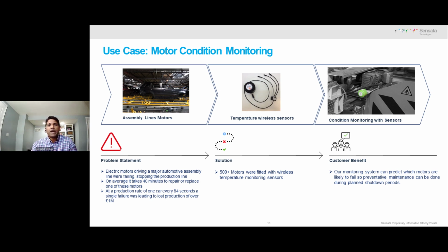To give you an idea, manual data collection with a handheld analyzer had been quoted at about 40 to 50K per annum for 1,200 sensors, which were taking data quarterly. So only 4 data points per asset per year, compared to one per hour for each measurement point that can be covered through an online condition monitoring system.